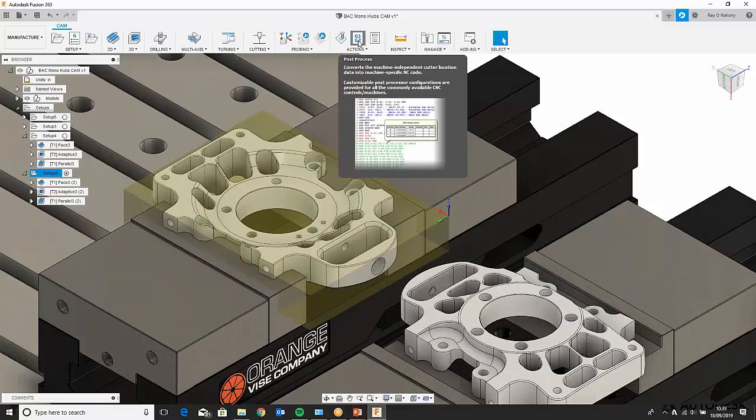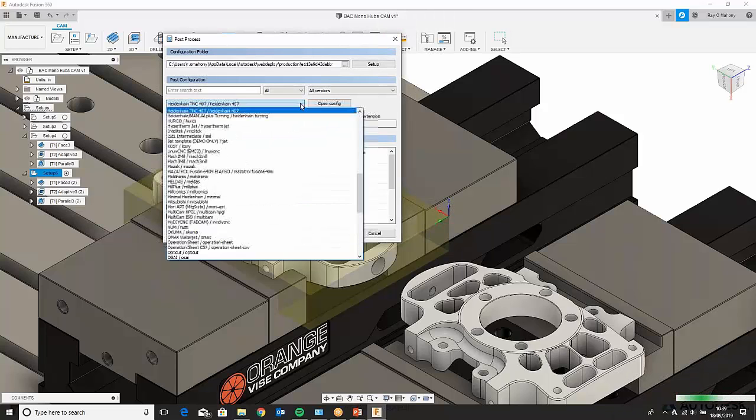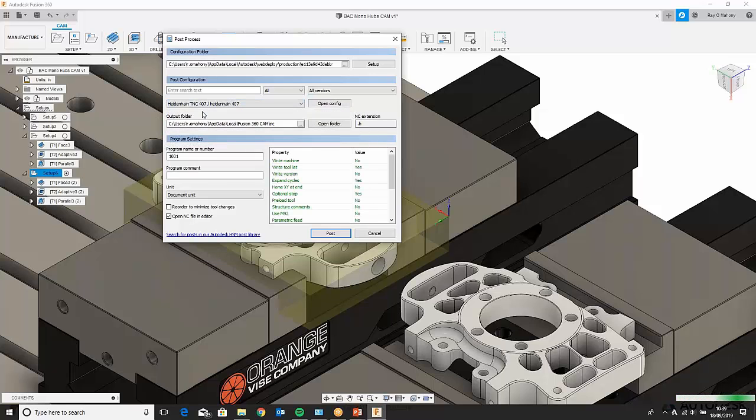Also what I can look at, just to see the post-process: how do we run with the particular post-process? What do we select? So again, in this information, you've got all these machining providers available to you and their post-process set up. Please bear in mind, these are templated post-processes. They will need to be edited as per your machining requirements in-house, but there is a stock of those available to you at any stage, and you can utilize those, and you can edit those if you're comfortable with editing a post-process for a machine. We've done slight editing in post-process here, especially on the 3-axis stuff, but the 5-axis stuff, you may need someone to do that for you, because that's quite detailed.